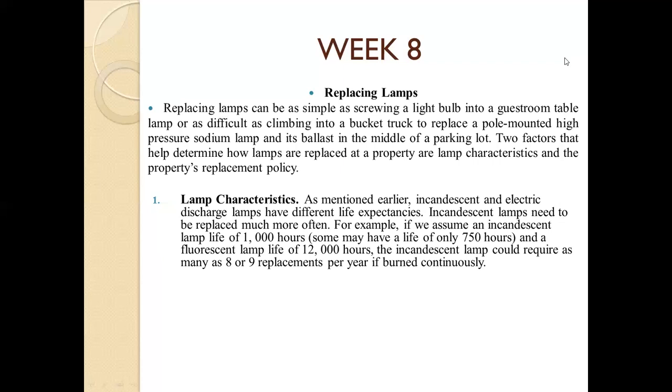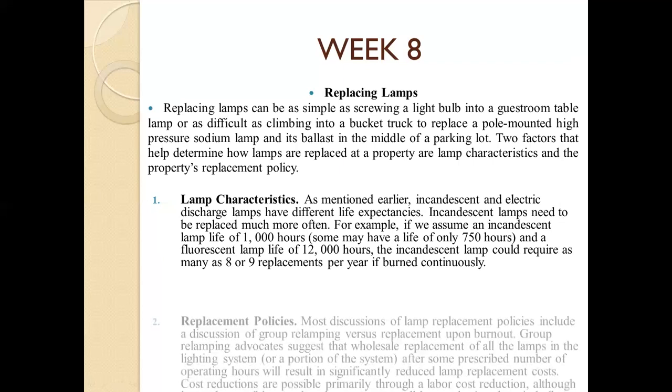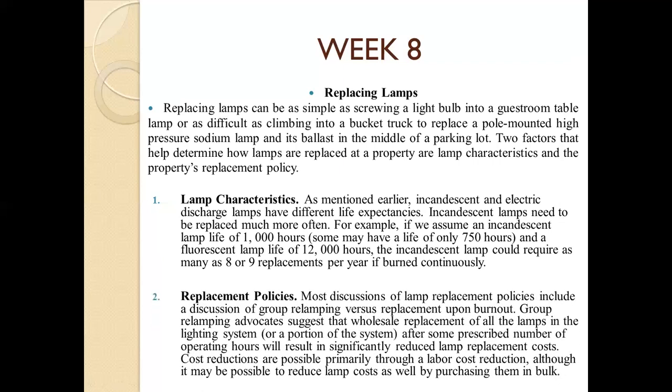Other characteristics of lamps that affect maintenance needs are the average burning time of the lamp and the voltage of the electrical supply to the lamp. Incandescent and fluorescent lamps that are frequently cycled will have greatly reduced lifetimes, resulting in greater maintenance costs in terms of lamps and labor.